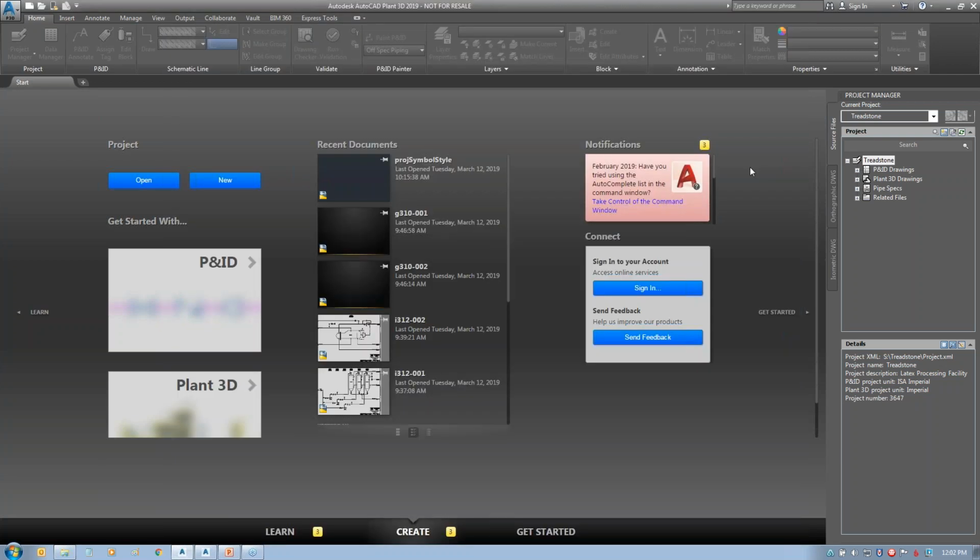In the meantime, this is the way I do process flow diagrams with Plant 3D, and normally I don't connect my equipment up to the P&IDs, because usually when I do PFDs, I'm doing them before I ever even do my P&IDs. They're usually done by the time I'm doing my P&IDs, so I usually don't worry about connecting the equipment up. But since I had support cases asking that, and that was one of the things they wanted on that particular idea, I decided to go ahead and make that a part of this, because everybody uses the product differently and has different procedures, so why not?